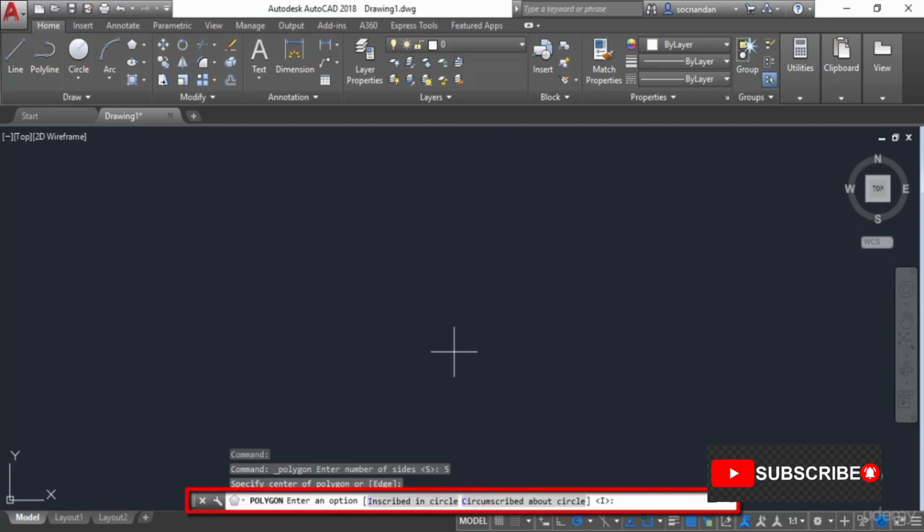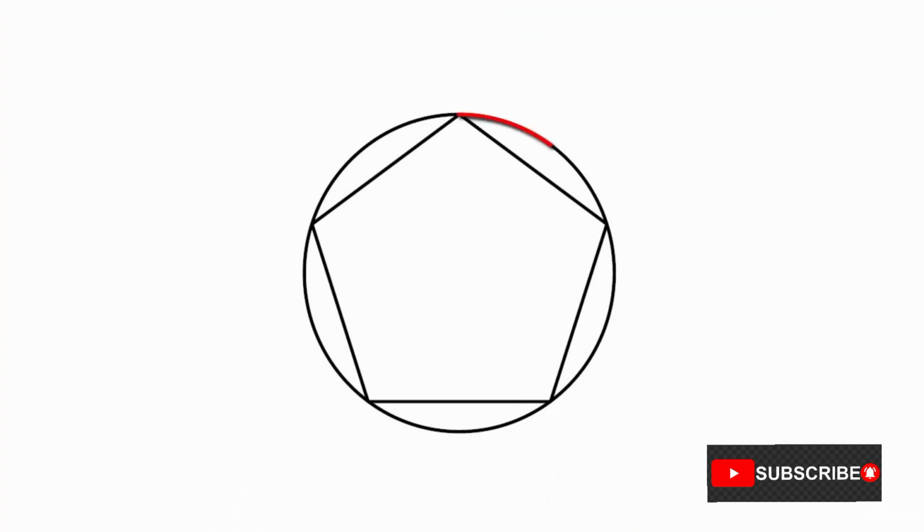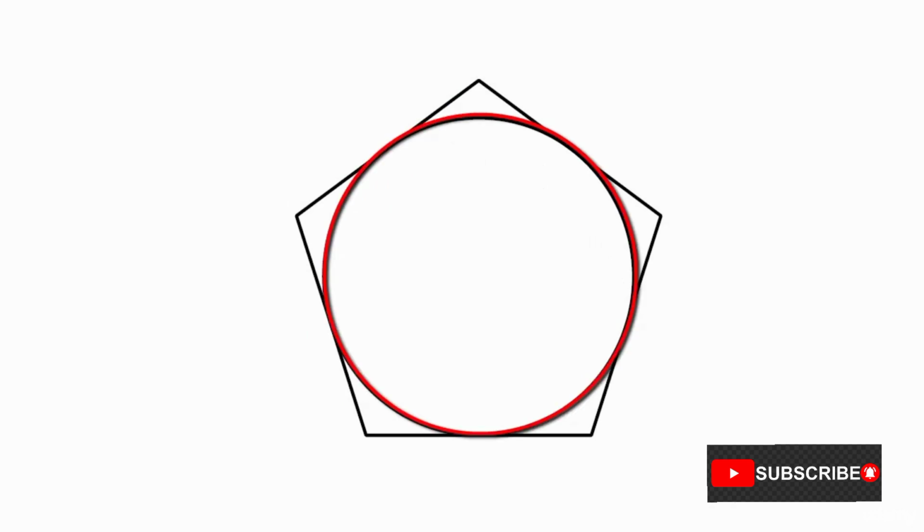And the command line now prompts you to choose one of the options, either inscribed in a circle or circumscribed about a circle. So if a polygon is inscribed in a circle, then that polygon will look something like this. So here we have this circle, and the polygon will be inside the circle in such a way that the vertices of the polygon will touch the circumference of the circle. But if the polygon is circumscribed about a circle, then the polygon will be outside the circle, and the midpoints of the line segments of the polygon will touch the circumference of the circle.